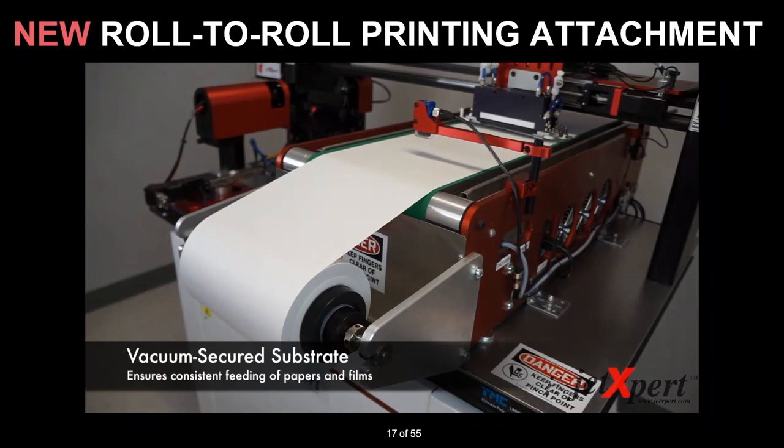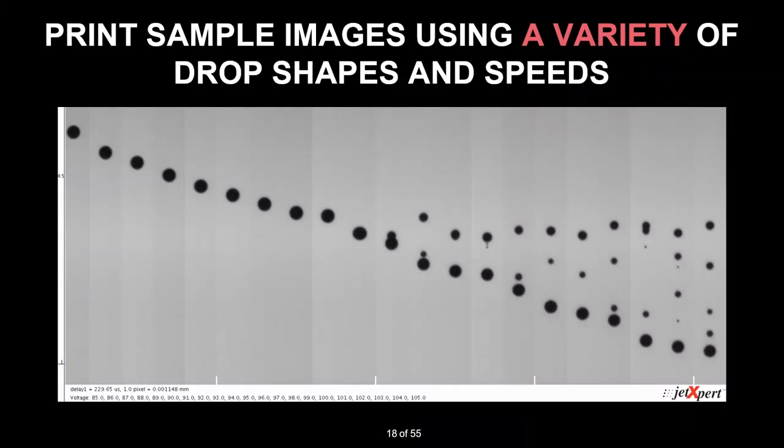Okay, so here's more of the technical stuff now on how to actually do this. What we did was we took ink and did a variety of different waveforms. So we have some that are slower but better drop formation, some that are much, much quicker, and you can tell the difference in speed. All these images are captured at the same moment in time. So the drops that are closer to the print head are moving more slowly, the ones that are farther away are moving more quickly. So we've got a whole variety of waveforms here with varying speeds, sizes, and levels of satellites.